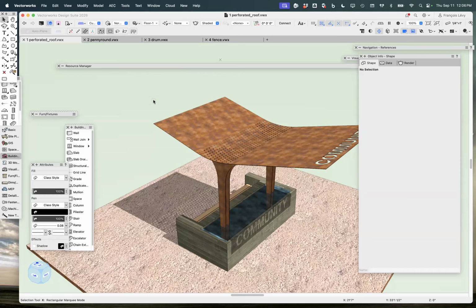So here's the array. If I double click on the array itself, by default, again, the base surface, that's that curved NURBS surface that we are arraying onto. And then let's look at the array items. If I select all and Control 6, you can see that I've got this 3D symbol that I've called hole 1 inch, very imaginatively named.